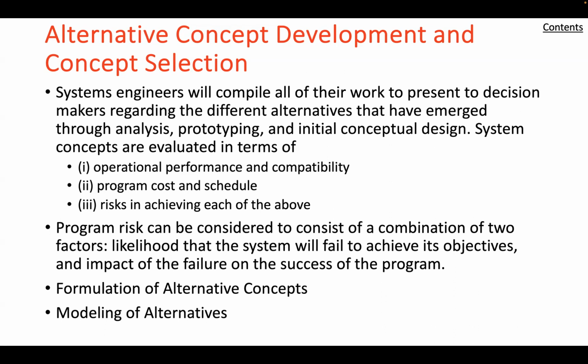A reduction in design margin is inevitably reflected in tighter restrictions on the environmentally induced changes in component characteristics during system operation and/or on the fabrication tolerances imposed in the production process. Either can lead to higher program risk, cost, or both. Accordingly, the issue of design margin should be explicitly addressed as an important criterion when selecting a preferred system concept.